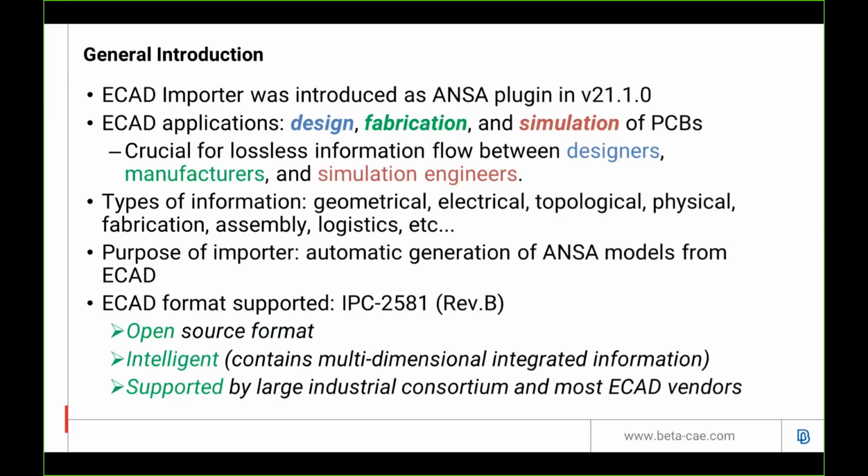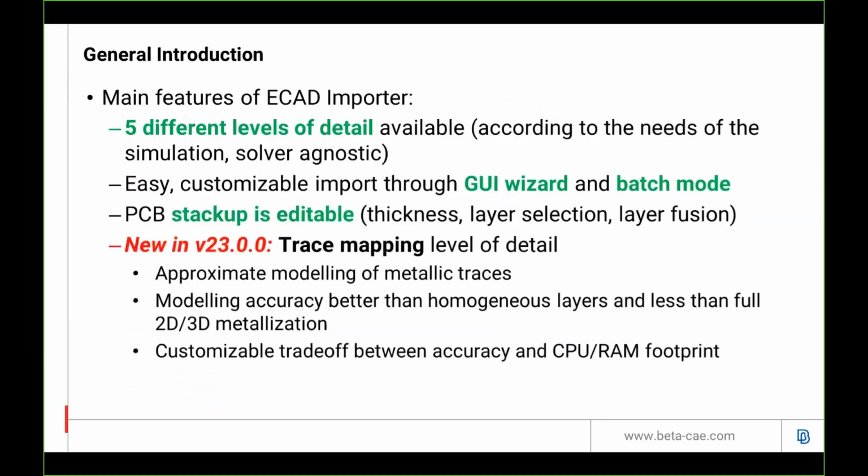The ECAD file format that is supported right now is the IPC-2581 revision B, which is an open source format. It's intelligent, and it's supported by a large industrial consortium and most ECAD vendors. The main features of our importer is that it supports multiple levels of detail according to the needs of the user and of the solver. So it's solver agnostic.